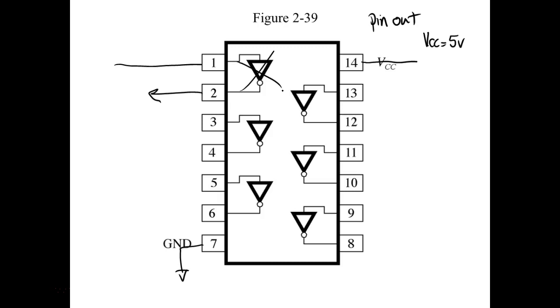That makes sense? Because if I'm going to use this IC, if I need 3, then I get 6, right? You understand? Because you can't split these circuits up. So a 7404 is what we call a hex inverter. Now, how did it get that name? Because there's 6 of them in there. We call the package a 14-pin deal. I can get AND gates in here. I can get OR gates. I can get NAND gates. I can get NOR gates. But this guy right here is an inverter.